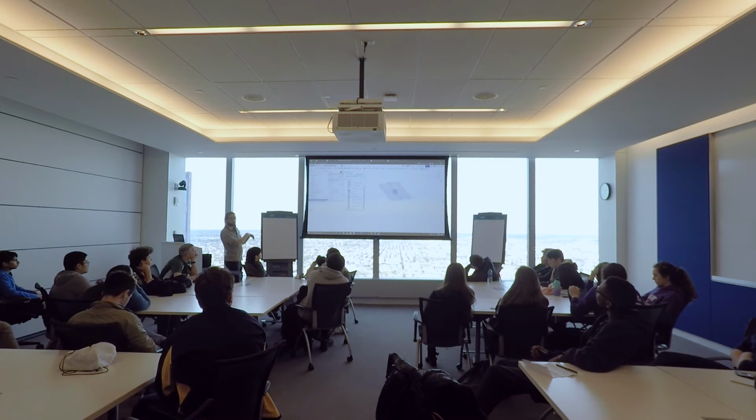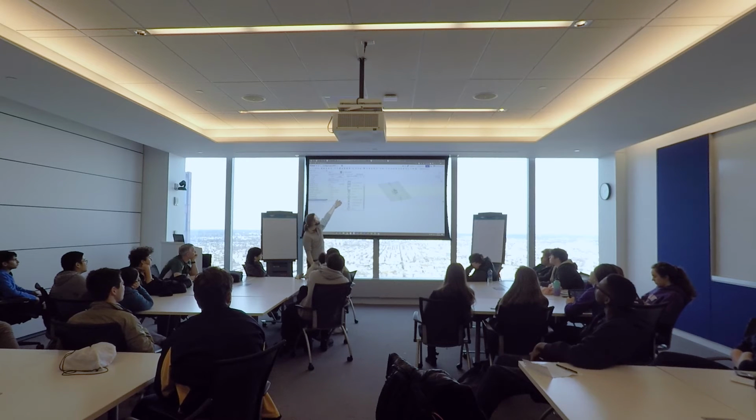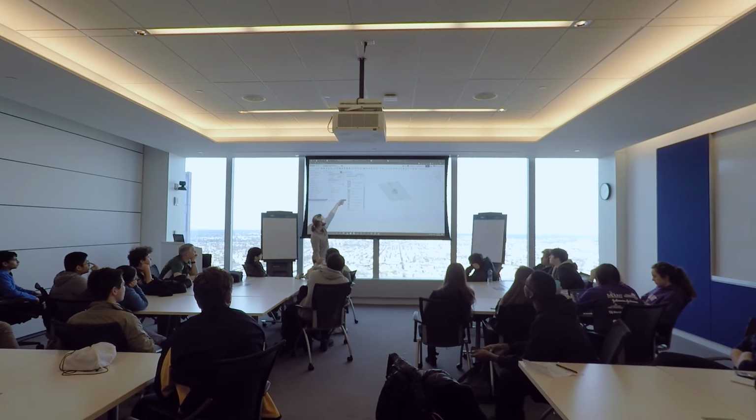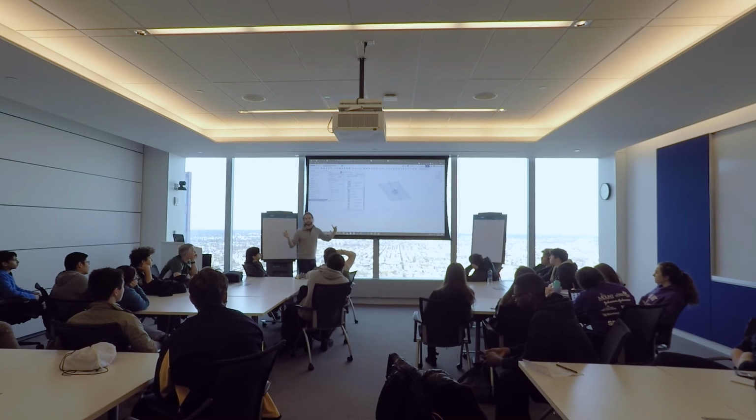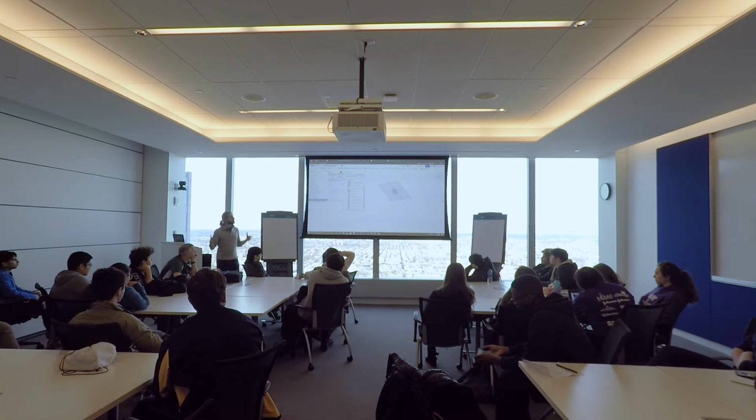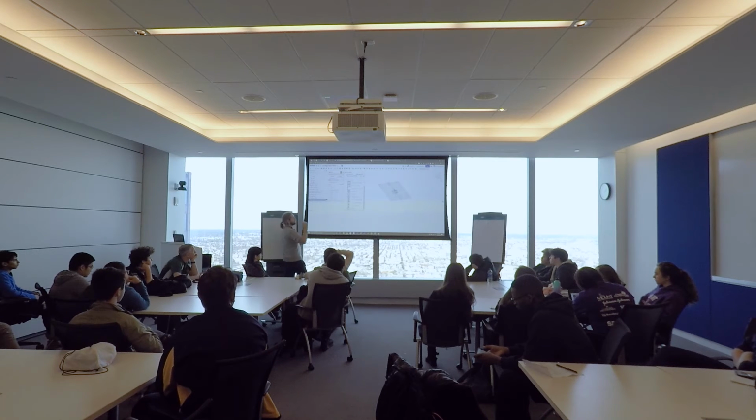And I use this for all kinds of stuff. So I have regular hex, I have churro, I have L angle 1x1, I have thunder hex. This sketch is centered on the tubing, this sketch is on the corner of the tubing, and this sketch is on the mid base of the tubing, so I can do all kinds of different locations for where tubing is. In this situation, I drew the complete outer perimeter of my robot, so I want to use the 2x1 100 corner tubing profile.